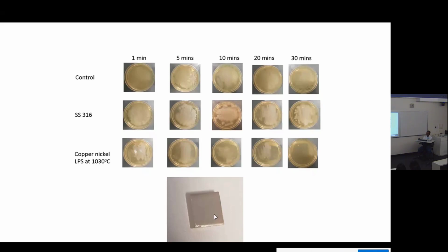And in an effort to be unbiased as well, SLM, the guys who use lasers to melt the material, you'll find that in some materials, particularly like titanium, they'll make it stronger than any other way you can make it. So whether it's rolled, forged, or whatever, they blow it out of the water. There's a bunch of characteristics to the process that mean that they're better than any other way you can make it.